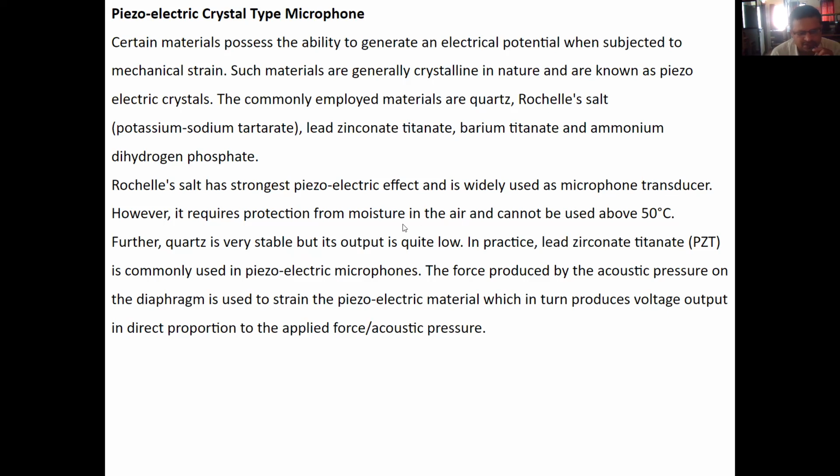However, it requires protection from moisture in the air and cannot be used above 50 degrees Celsius. Further, quartz is very stable, but its output is quite low. In practice, lead zirconate titanate (PZT) is commonly used in piezoelectric microphones. The force produced by the acoustic pressure on the diaphragm is used to strain the piezoelectric material, which in turn produces a voltage output in direct proportion to the applied force or acoustic pressure.